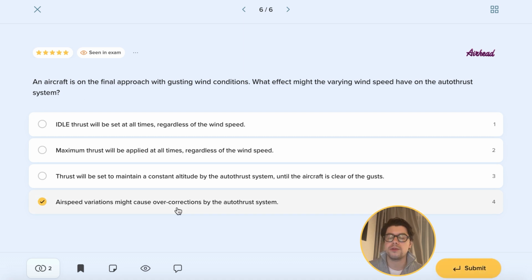And also here, I'll say that the Airbus aircraft has also a system which connects the ground speed of the aircraft, which is taken by the GPS, with the computer. It is called ground speed mini. It will try to maintain a constant ground speed instead of the IAS if we have these very, very gusty winds. So this system is very smart, and it will allow you to fly a very smooth and safe approach, even if the winds are varying strongly, as it will mainly focus on the GPS data and the speed that you are flying according to these receivers.